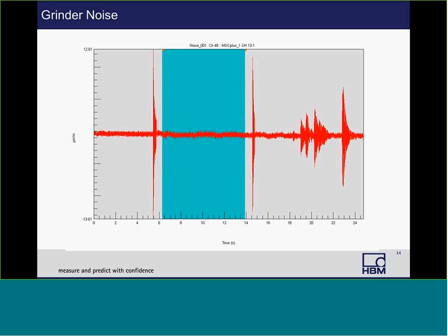On this little demo that I did, the lead wires to the actual strain gauge are not shielded, which would be very typical when you're running strain gauges. The small lead wires up to it are usually laid in parallel and are likely not shielded, maybe just have a covering. So what I did is I took the right angle grinder and I pulsed it on and off, and it created these large noise spikes you see here.